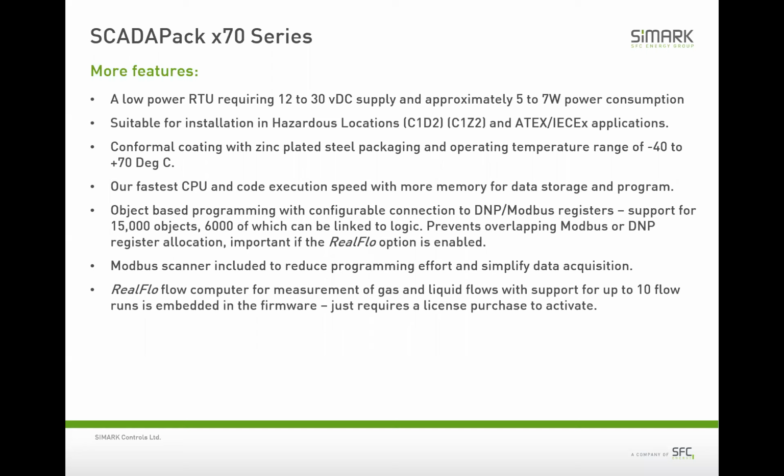Also included for a license fee is the ability to use RealFlow, the flow computer, the measurement there on the RTU. We're not supporting C programs on this RTU, so Schneider has embedded the RealFlow flow computer into the firmware of the RTU. And then we're supporting up to 10 flow runs, so we're not differentiating between water or gas or liquid, just a flow run. It's in 3 groupings up to 10 for licensing. So you just purchase a license, put that on the RTU, and you will find the RealFlow can be enabled.